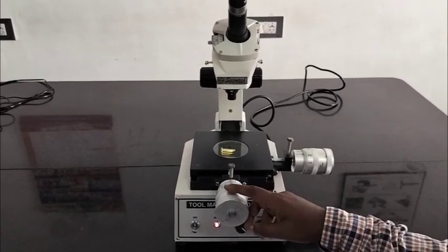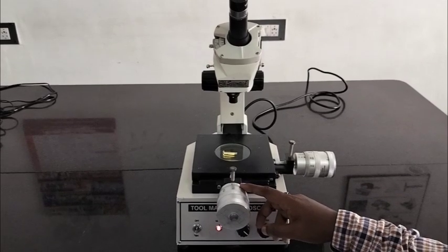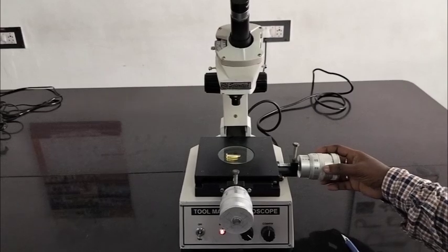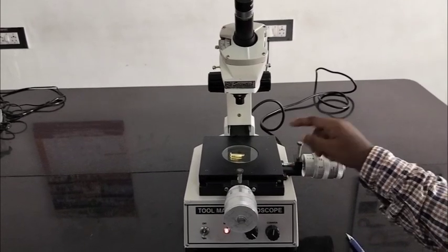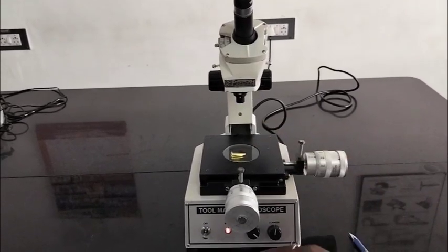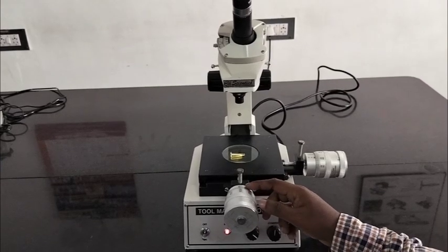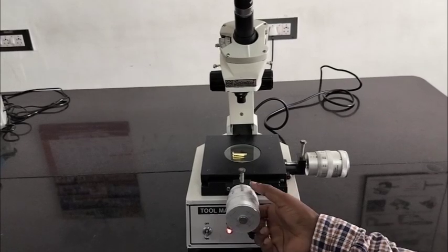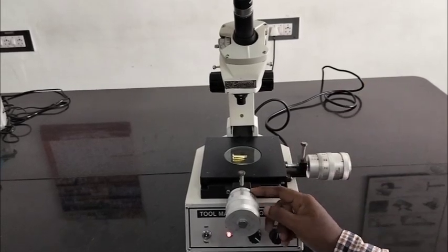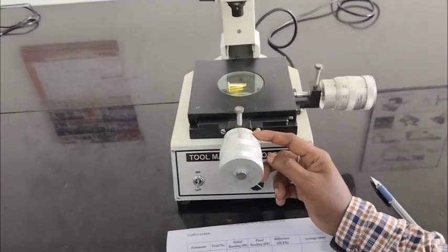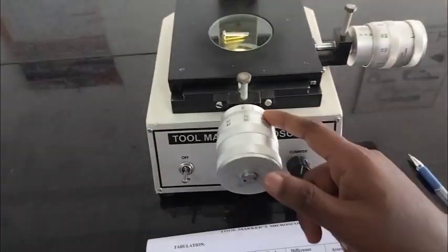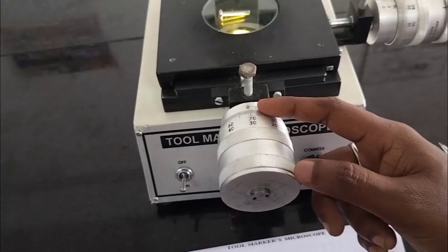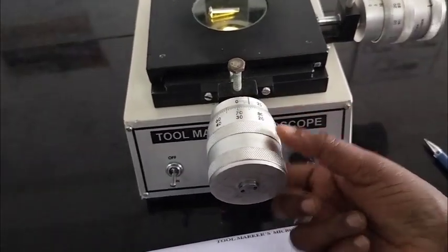In this micrometer we analyze the outer diameter and inner diameter, and this type of micrometer can also be used to find the pitch of the screw thread. So now we have to calculate for this. Initially we fix the reading at 25 mm for the outer diameter. The outer diameter of 25 is the initial reading to be noted here. After that we move outwards and remove it.